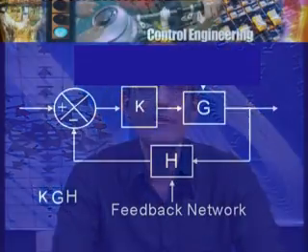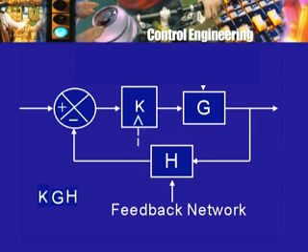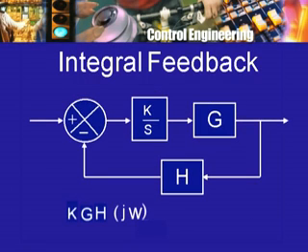The simplest thing to do is, of course, change the gain K, and that was the case we studied first for the case when we had just proportional feedback, but the amount or the proportionality constant k here could be changed. The second thing that we did was not just have k here, but change the transfer function to k by s, that is introduce an additional transfer function here 1 by s, corresponding to the integrator. Now, that resulted in certain changes and certain consequences of that, such as the system could become unstable for a value of k greater than some critical value.